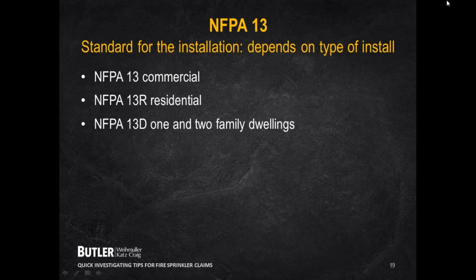Now, there are 3 different types of NFPA 13 guidelines. The plain NFPA 13 applies to all commercial settings. That's where your occupancy is a commercial loss and not a residential loss. And then the NFPA 13R is for the residential, and those are the rules pertaining to that. They have different requirements.